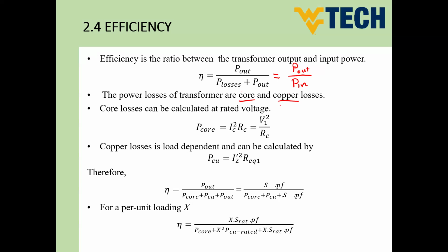Now, the core loss can be calculated at rated volt. You remember, guys, in the previous class when we discussed the open circuit and short circuit tests, we mentioned that the open circuit test has to be made at rated volt.